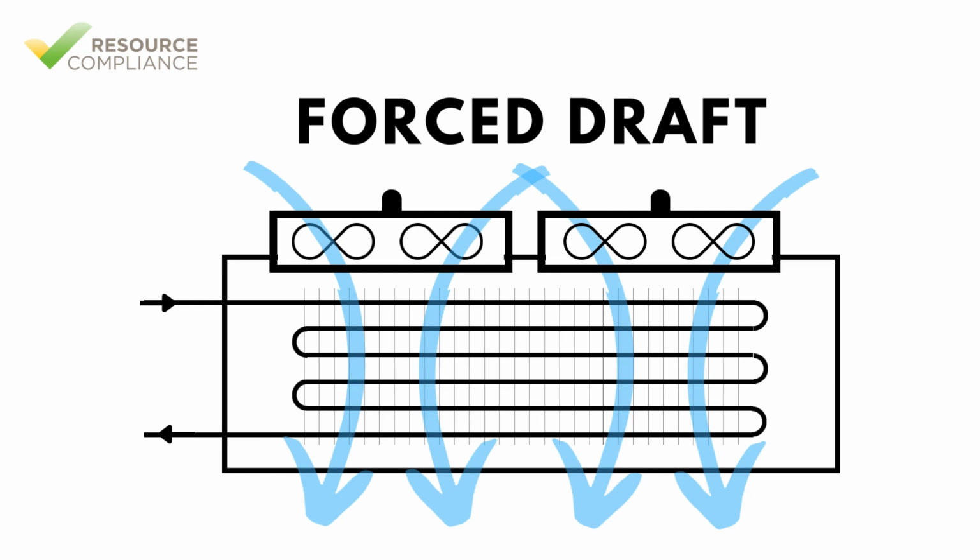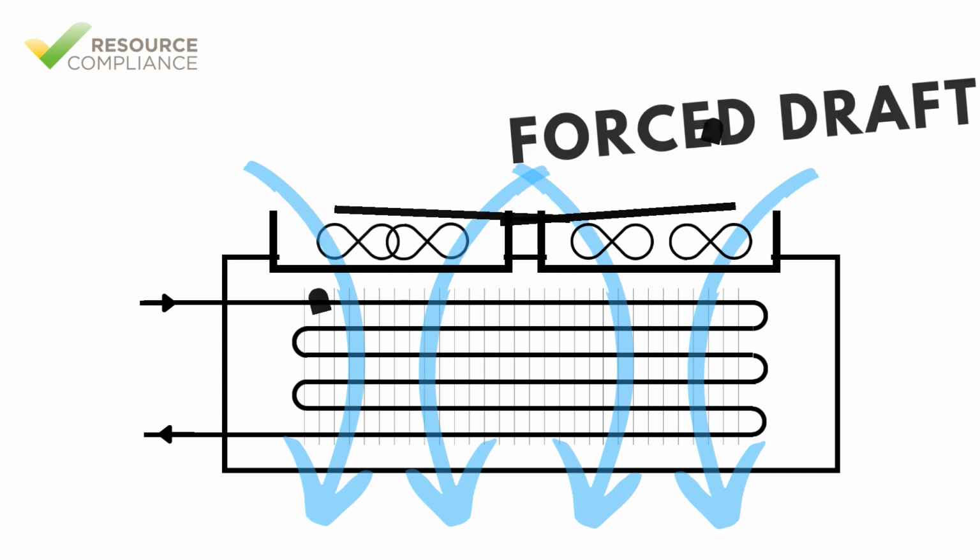The pros and cons of forced air evaporators are the opposite of induced draft. The advantage of this approach is that heat from the fan motors can be absorbed by the evaporator before distributing the air throughout the room. Forced air through the coil, however, does not result in a uniform distribution of the air across the coil, which is a downside of the forced air approach.